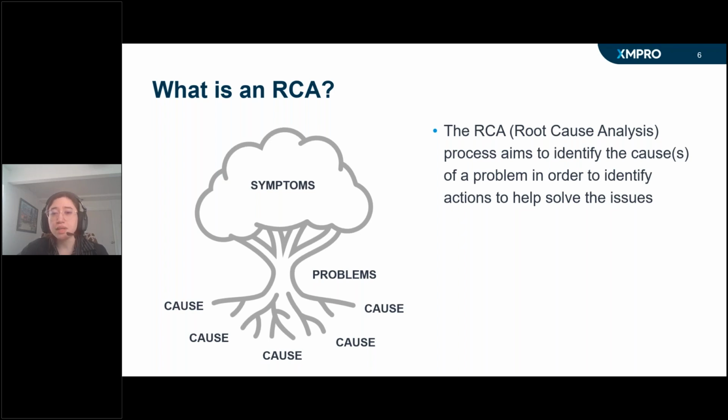So at a high level, right, you want to be identifying the actual causes of a failure, not necessarily the symptoms. As shown on the diagram on the left, the symptoms are typically what you actually see, i.e. a pump bearing has locked up, but why has the pump bearing locked up? And so through the root cause analysis process, the aim is to address these causes and not necessarily just the symptoms.